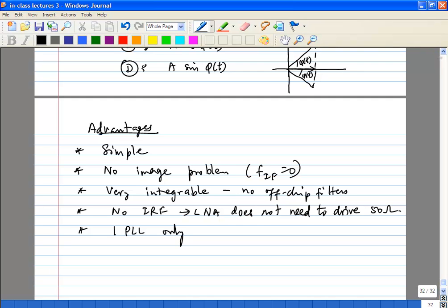No, definitely, yes. It definitely helps with that. I would say the number one issue is the noise figure, but you can integrate part of it into your band select filter. But if your IF image falls inside the band, then that's a problem. Apart from that, there is no particular reason why you can't do that, except for the noise figure part. The noise figure part is huge. That is a big problem.